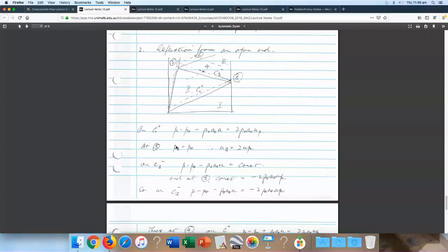So in the flow that I spoke about, where it was a two-dimensional flow, I had a center line and I turned the flow down. Well, there's a solution for that, which would be an oblique shock wave, and the flow is supersonic coming in and supersonic coming out. And everywhere the flow coming out, if it's been through that single shock, has turned the same angle. So it's compatible with a solution that has a wall like that. So that's an attached shock.